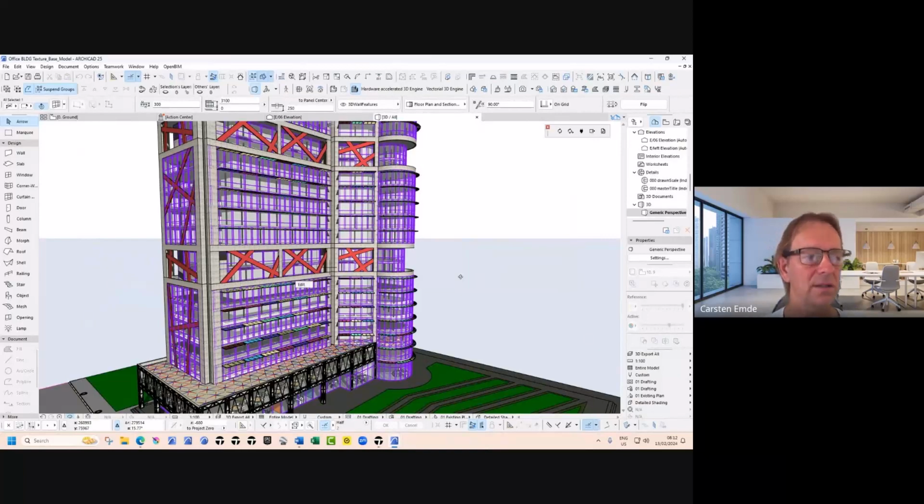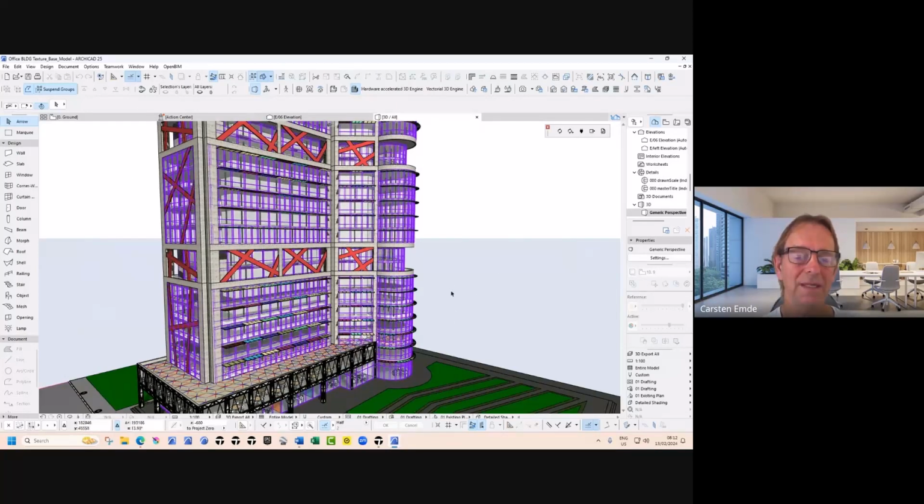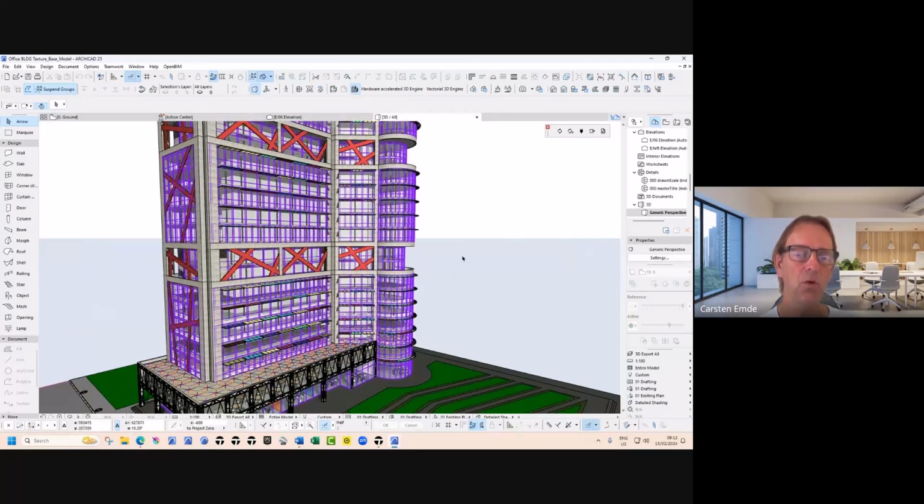I've got lots of glass here. So in theory, I'm using ArchiCAD, but in any other CAD model too, you can give one glass material, which sort of makes sense. Everything is glass, that's fine. Just get it over into Twinmotion, and I apply one glass material, and I'm happy. Now, the drawback with that, as I will show you in a minute, is that sometimes you need more or less reflection, depending on your camera location, depending on your light, also depending on what you want to show.